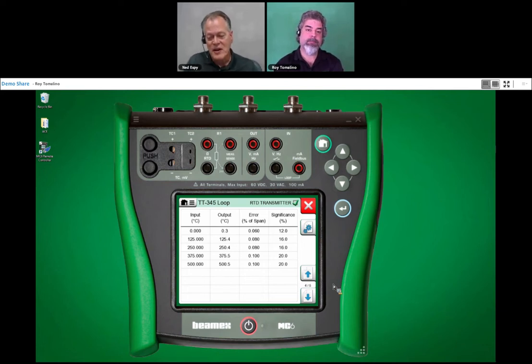We have a customer that has a batch process with 6 zones. So he's got 6 RTDs coming into a PLC, 6 PLC inputs. And he was having all kind of quality problems. We used a dry block and looked at the PLC readout. He was putting in offsets so that all 6 zones were identical to that dry block temperature versus the readout.